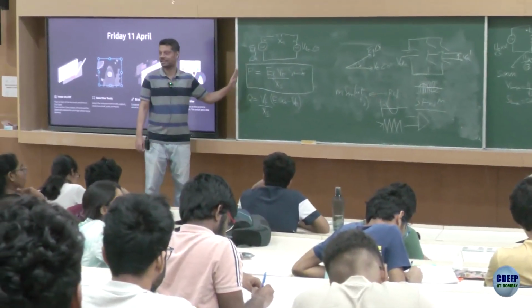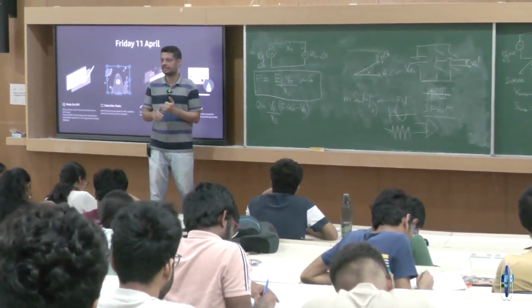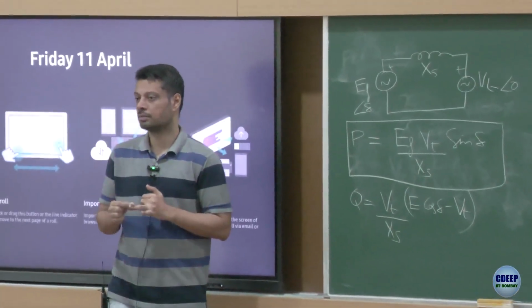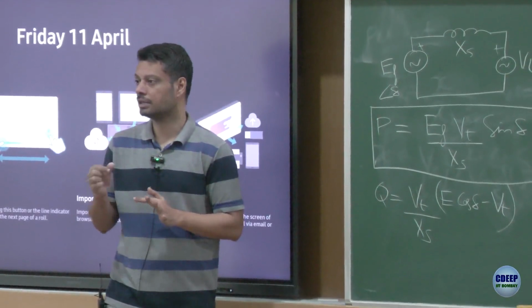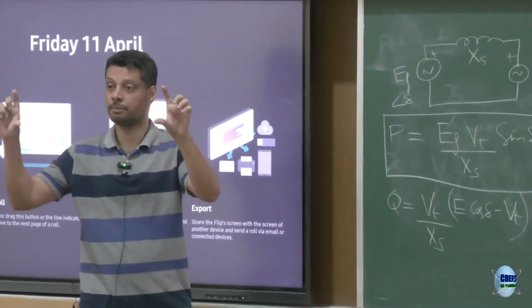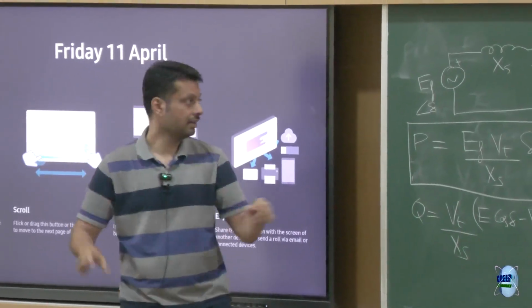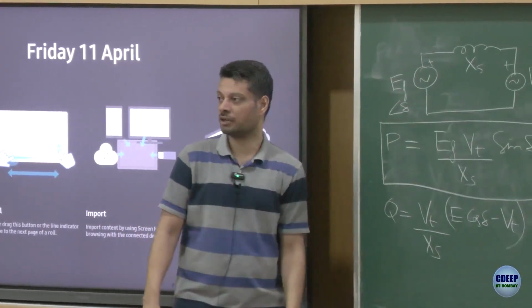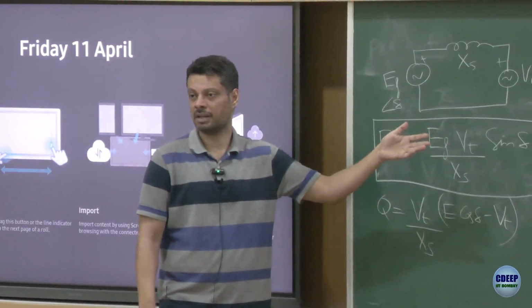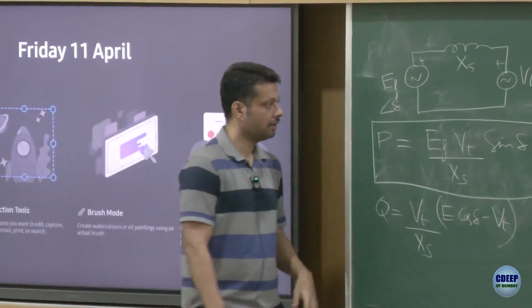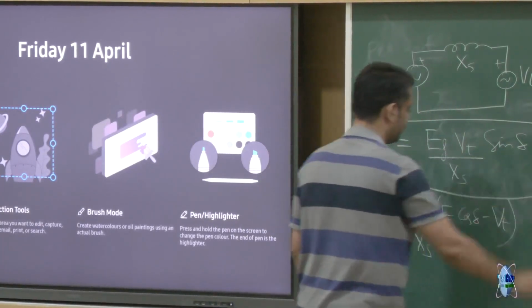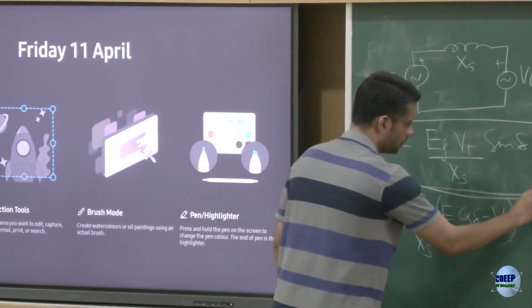Okay, so this is clear. Any source you see, anything connected to the grid, be it storage, be it solar power, be it a wind turbine, be it a hydro, be it a steam turbine, be it just analyzing two different points in the grid connected through a line, this kind of architecture is very, very common. So whichever source is leading supplies power, whichever source is lagging absorbs power. Okay, if this part is well understood, let us go and look at this part.